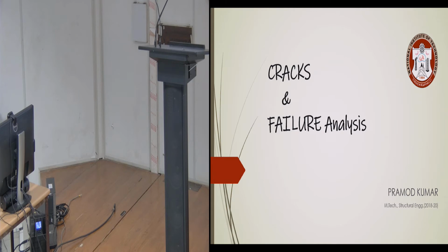According to the photographs, we try to find the causes of the cracks. The causes may be based on eyewitnesses. Suppose we are not getting eyewitnesses, then we can guess, or rely on tests, so many tests, NDT as well as semi-destructive tests.